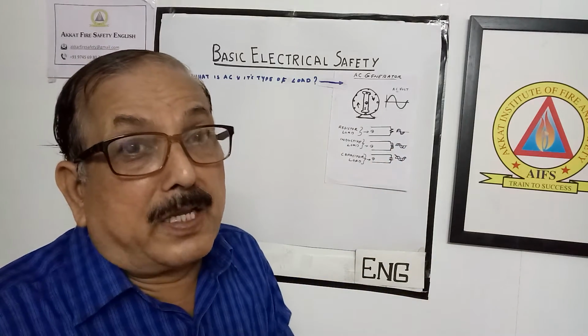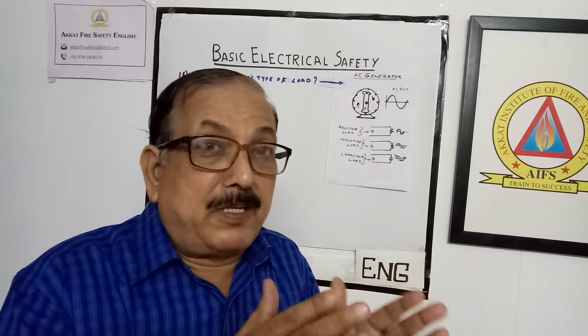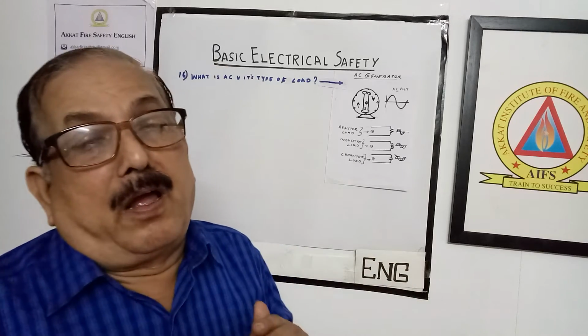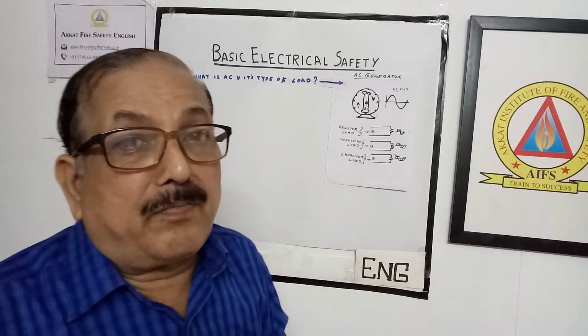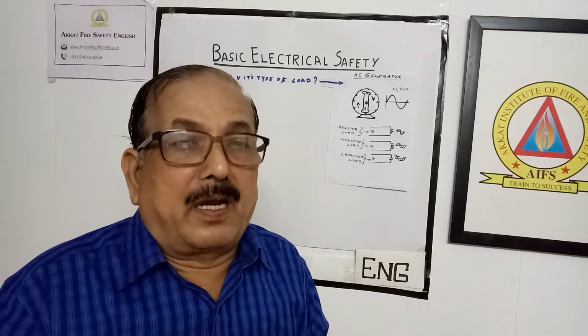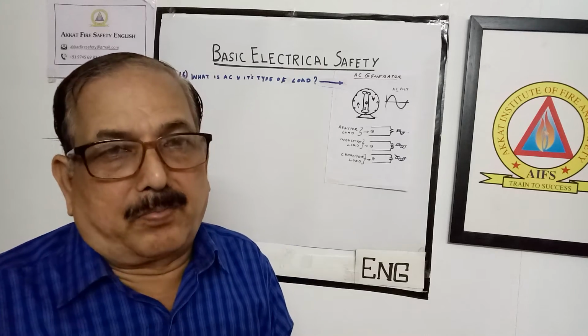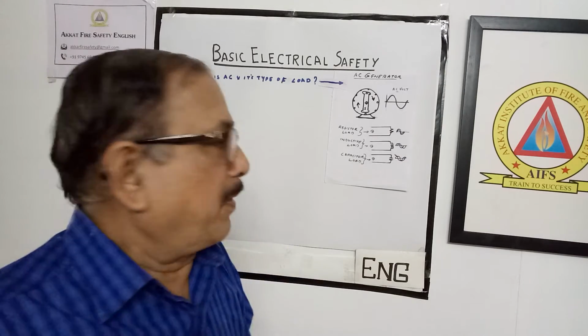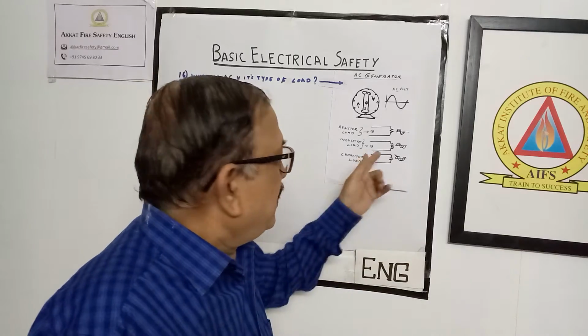So such type of load is the inductive type load. Here there is a phase difference between current and voltage. That phase difference we are measuring, and the cosine of that phase difference angle is the power factor. So that is inductive load.